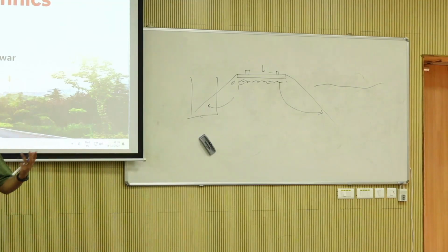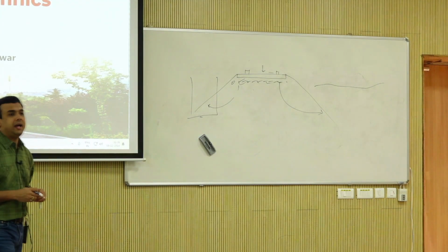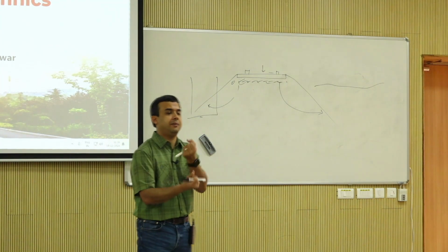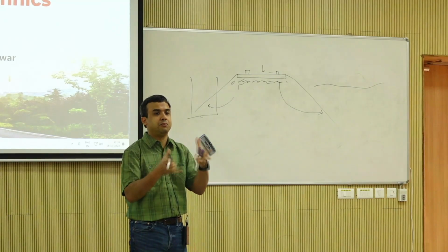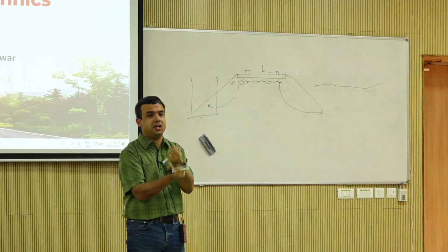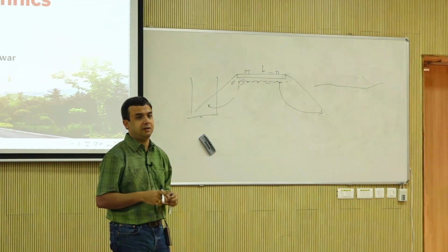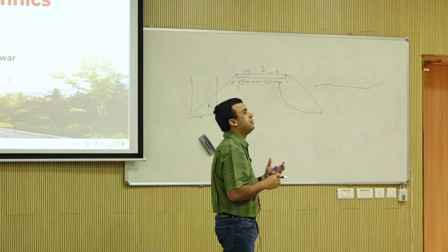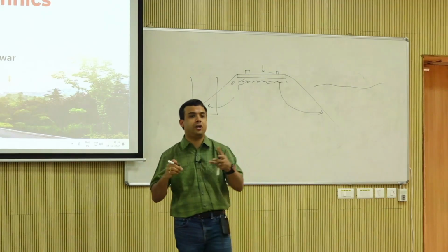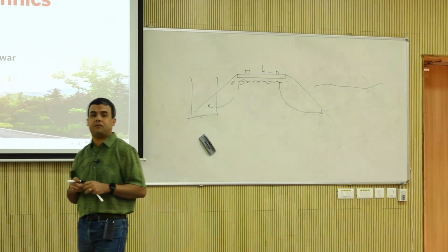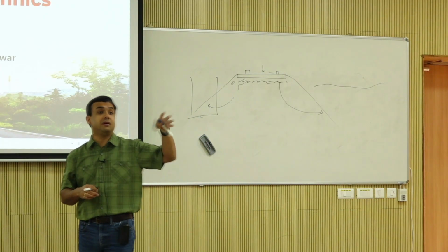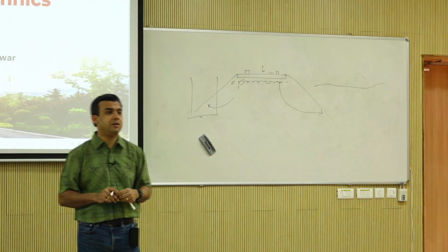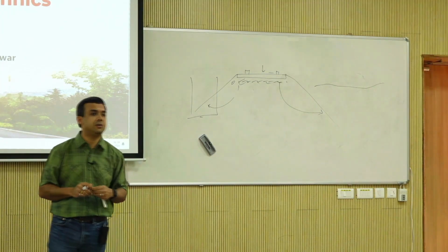There is an abundance of wood, and it's more absorbing. It's not as rigid, so it doesn't degrade the ballast as badly. But when you go to higher speed, higher demand, like the Northeast Corridor, where Amtrak runs a lot of the passenger service, there are a lot of concrete ties, but a lot of timber as well.